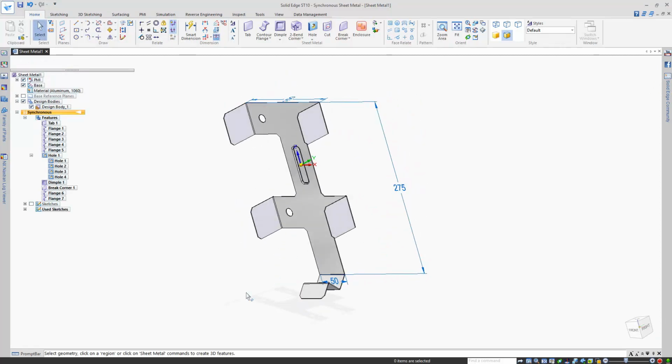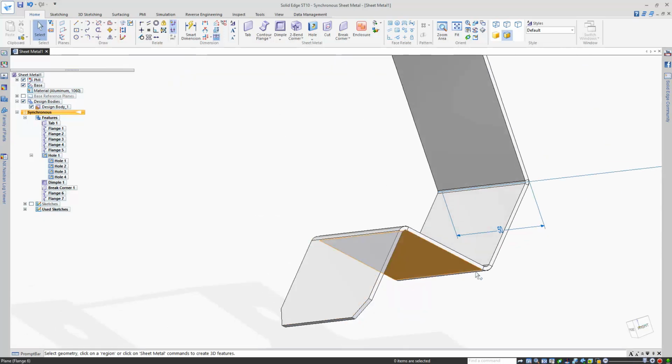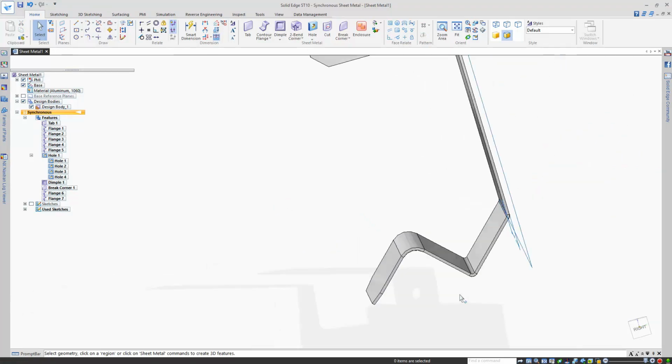being edited. Sheet metal parts have bends in them, as you may know, and by default bends have a radius assigned by their material properties. However, this can be overridden by selecting a bend, choosing the radius callout, and then entering your own value. However, I'm not happy with the angle this entire jog's been modelled at, so let's move it.